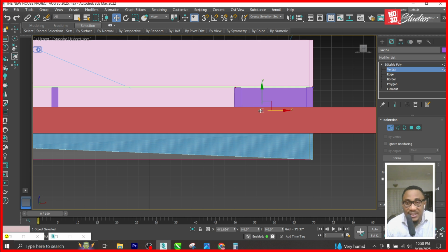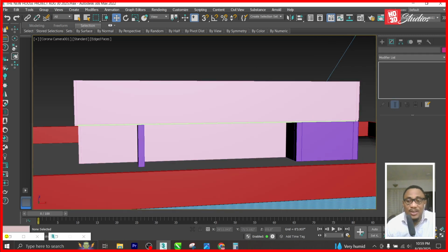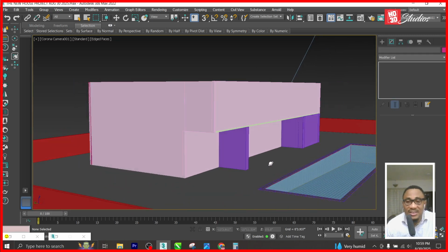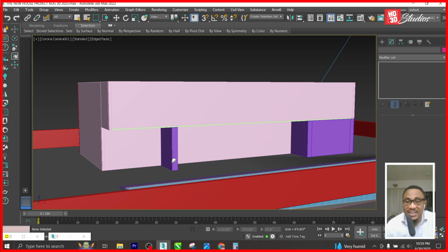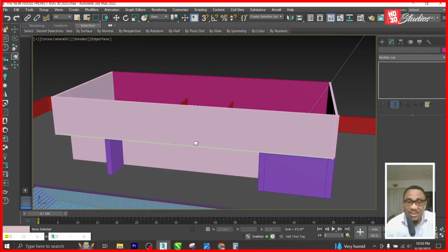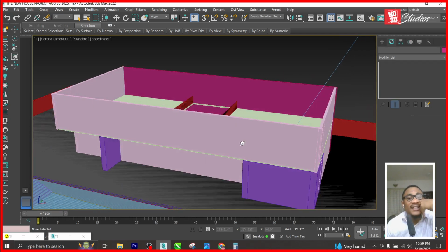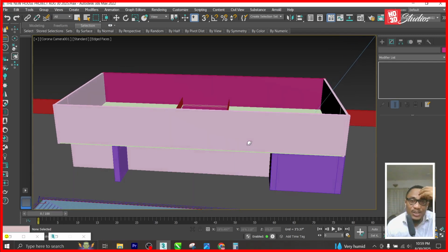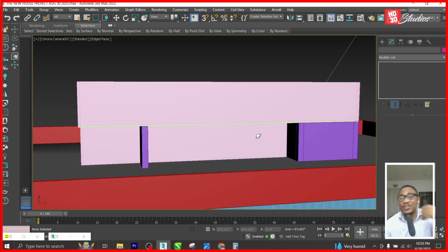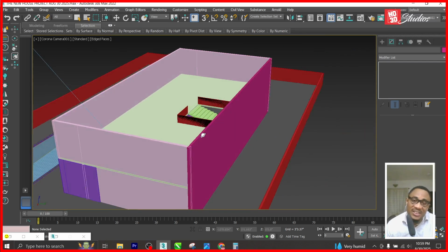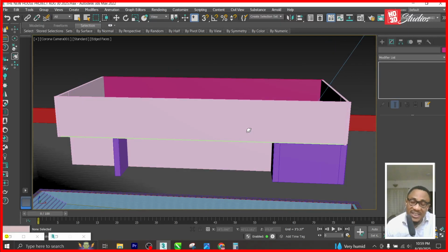So designers naturally make tweaks. If I draw it this way and I don't like it, then I try something else. So now what I have done is something is carrying the cantilever here, and this is also carrying all of the building here. So even if you had a balcony here, you would still be comfortable that you're not suspended on a 100-foot cantilever. It can be designed. It's just going to involve a lot of structural elements, and it would give a structural engineer a headache. But it's doable. I've seen crazy cantilevers in different parts of the world, so I know it's doable.